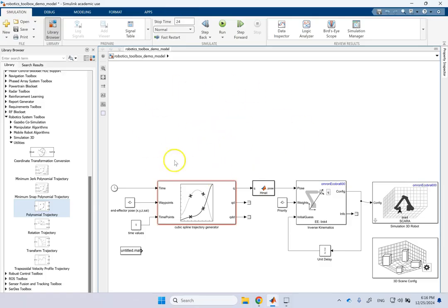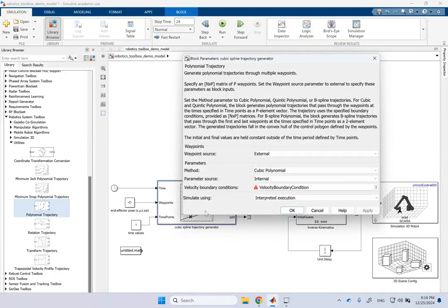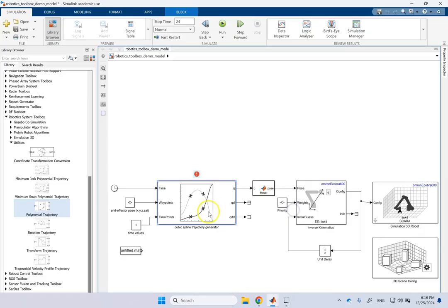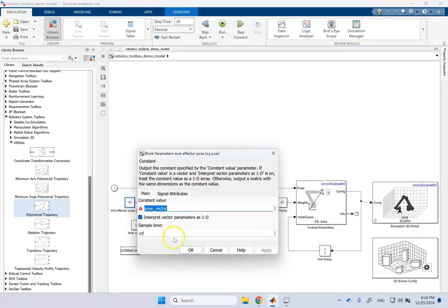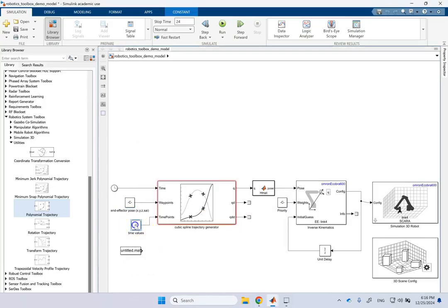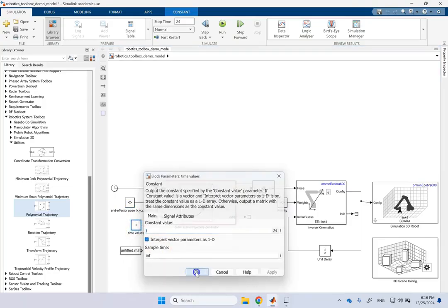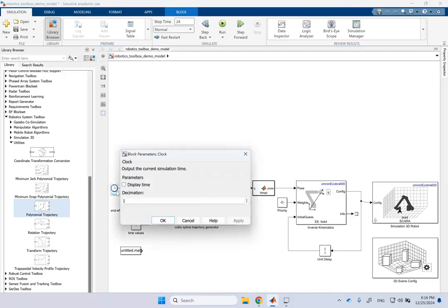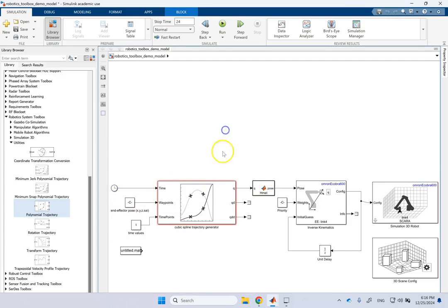So instead of doing that code that I showed you that finds the coefficient matrix, the right-hand side, and a for loop to perform and increase the number of data points, all you need to do is to use this block. Simple as that. Very, very simple and very fast. Okay? And if you look at this end effector, you see sample time infinity, time values infinity, but if you want, you can sample them every 0.1 of a second or something too, but this is good. So here it spits out Q, Q dot, and Q double dot. We don't care in this project about velocity and acceleration. All we care are the Qs.